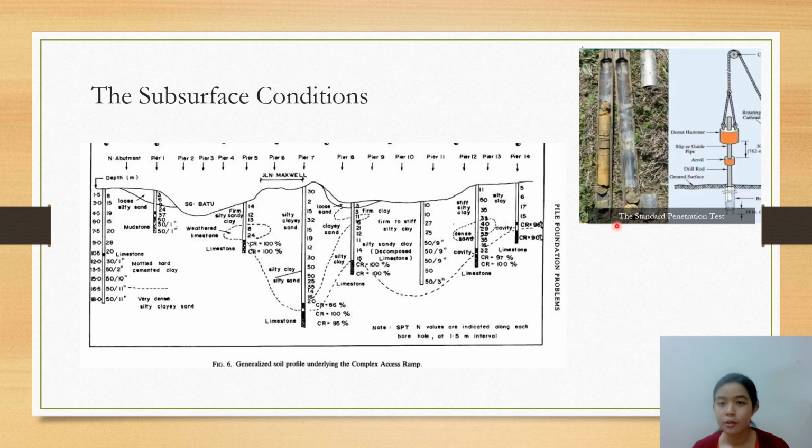This is the figure for the standard penetration test. And once the drilling reached the bedrock, diamond core drilling was carried out for another 5 meters in order to look for cavities in the bedrock.